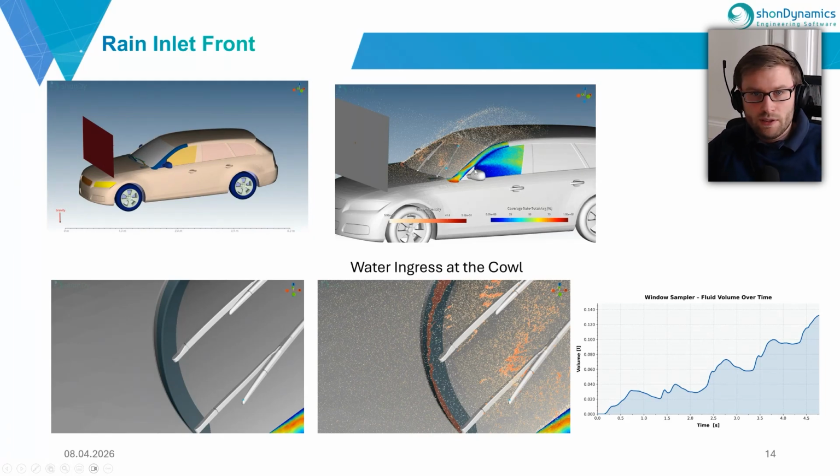And then you can also compare how the fluid distribution looks in this kind of setup. So you have a wind shadow of the mirror. This more or less protects the fluid from hitting the sidewall, but then you have an accumulation on the A pillar of this fluid, and then from there to the side window of the driver seat.